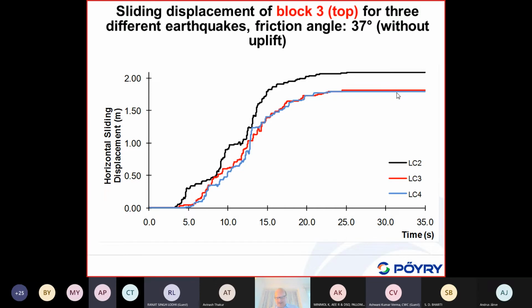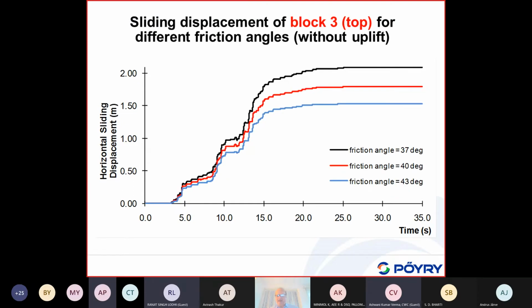But in dams, we basically say you should use at least 3 as a minimum of acceleration time histories, and these acceleration time histories are sensitive, especially in nonlinear analysis, as we are explaining here. Just to go through that.